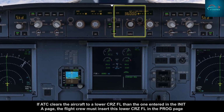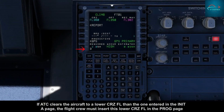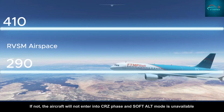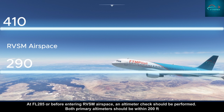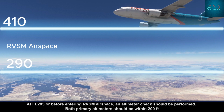If air traffic control clears the aircraft to a lower cruise flight level than the one entered in the initialization A page, the flight crew must insert this lower cruise flight level in the progress page. If not, the aircraft will not enter into the cruise phase and soft altitude mode is unavailable. At flight level 285 or before entering RVSM airspace, an altimeter check should be performed. Both primary altimeters should be within 200 feet.